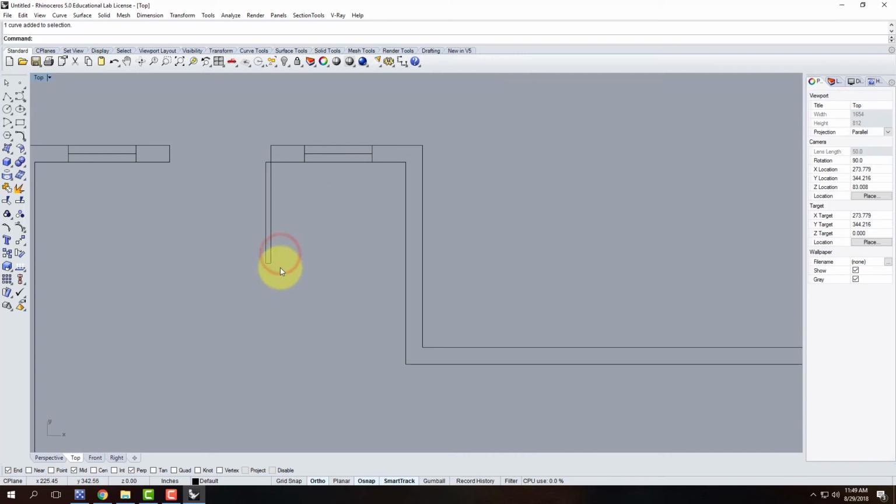The last piece of this would be to create the door swing. I'm going to use an arc to do that. There's an arc tool here. I don't like the default one that's showing, so I'll click the triangle next to the arc. It's the tool right below the circle if you're looking for it. And instead of picking the first one, I'll come over a couple and use the arc start, end, and direction. So I'll pick that third one over, which allows me to pick the start of the arc, the end of the arc, and the direction. It makes creating that door arc really easy.